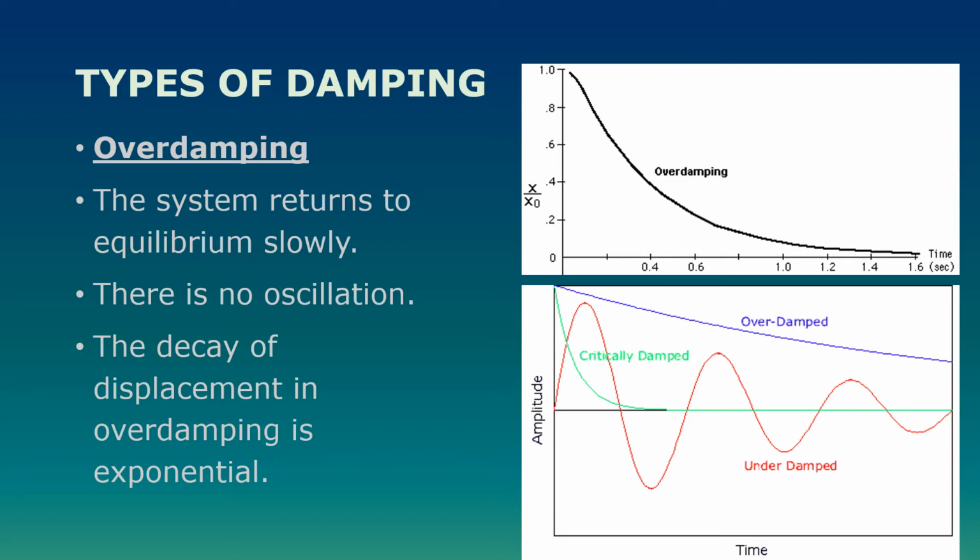You can have heavier and lighter overdamping. So just bear that in mind. If it's heavier overdamping, it will take longer to return to equilibrium than light overdamping. So heavy and light describe the speed at which these things return to equilibrium. But the terms for these crossover points are under, critical, and over, and they're the ones that you need to know.